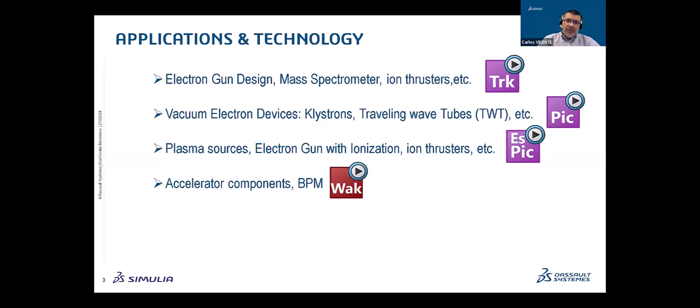There is another approach, which is our Wakefield solver, also a different approach in time domain. In this case, we are considering a particle beam as a transient excitation, and one can calculate the so-called wake fields to characterize the RF components from an accelerator, for instance. The particle beam is defined as an infinitely thin straight line, which takes into account its properties.